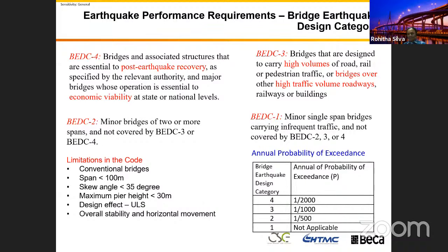Like I mentioned, when you are designing the bridge, everything is related to this bridge earthquake design category. Now you can see how important it is to understand that, especially when you are designing. It's not designing for an earthquake. It's designing a particular structure to sustain that earthquake loading, and making sure that we design and detail for that particular case, so that the structure of our bridge is serviceable after an earthquake.